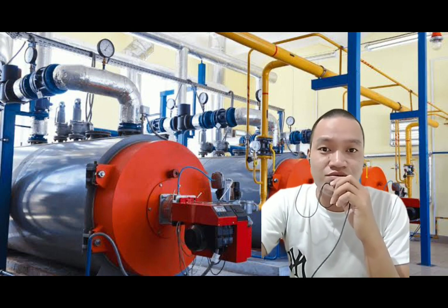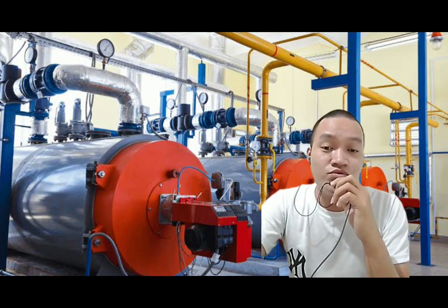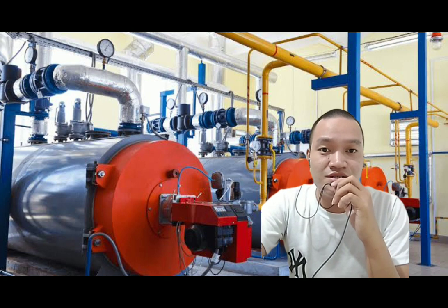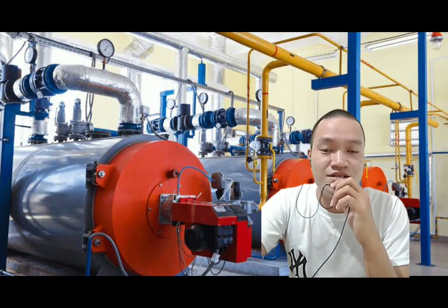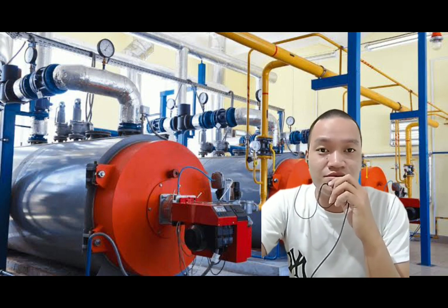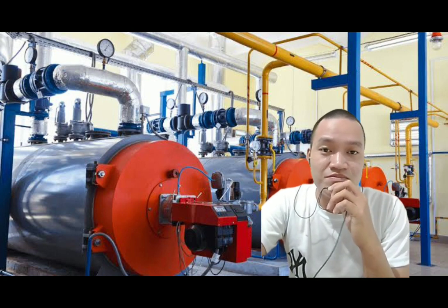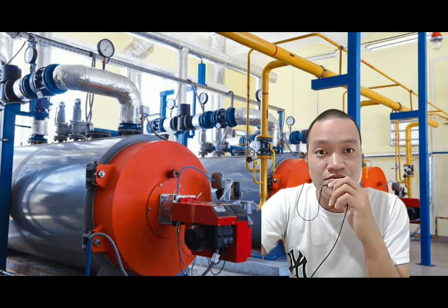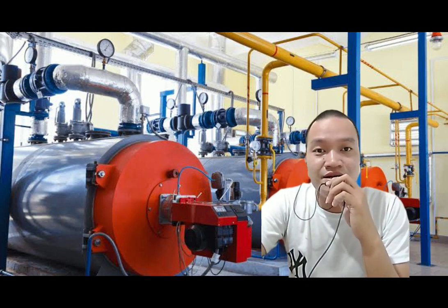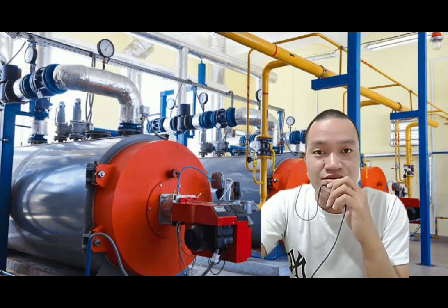Then wait until the water reaches 40% to 50%, which we can see in the water level gauge. If it reaches service water level, press the stop button and turn off the feed pump button. After that, we are now going to supply fuel to the burner in the boiler. First, we open the fuel supply valve and air dampers before starting. So if all are ready and okay, push the start button in the control panel.